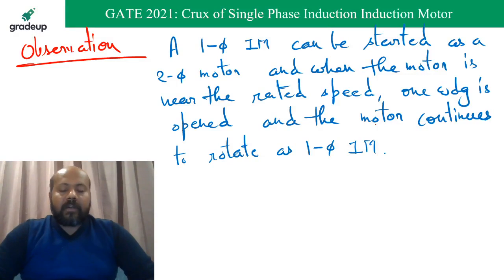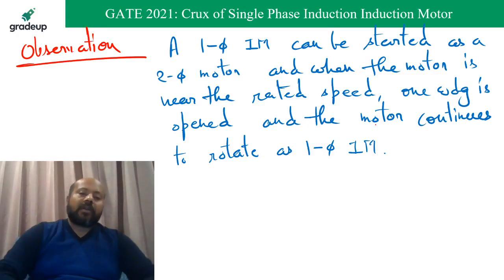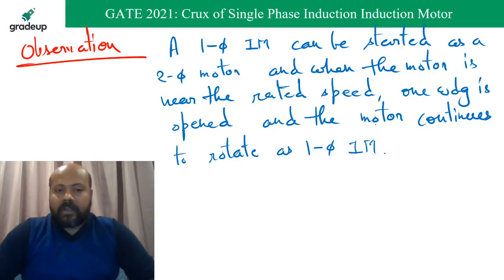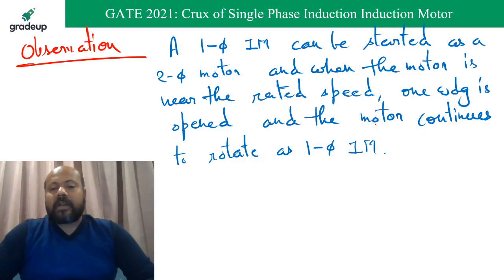The best idea we are using right now is based on the fact that a three-phase motor is self-starting, because it has a rotating magnetic field. Similarly, a two-phase motor is also self-starting because there is a rotating magnetic field. But a single-phase induction motor is not self-starting, because it does not have a rotating magnetic field. Rather, it has a pulsating field, which we divide into two parts, the forward field and the backward field.